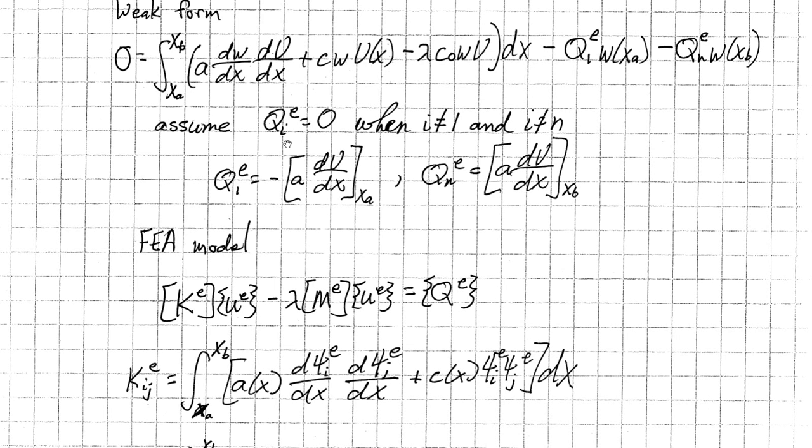Alright, we're going to assume zero flux on the surface and no internal heat transfer. More specifically, we're talking about internal heat transfer, not on the external boundaries. So that's why I say i equals 1. i equals 1 typically will mean the left-most point of a bar, and i equals n would be the right-most endpoint. Those 2 points are defined here. So again, we could have flux on our external endpoint boundaries.